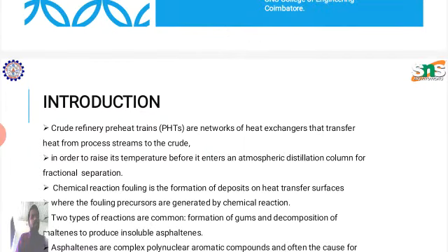Following the introduction of the fouling threshold concept, the semi-empirical approach originally introduced to evaluate the rate of crude oil tube side fouling at a local point condition describes the fouling rate as the combination of a deposition term and a fouling suppression term.